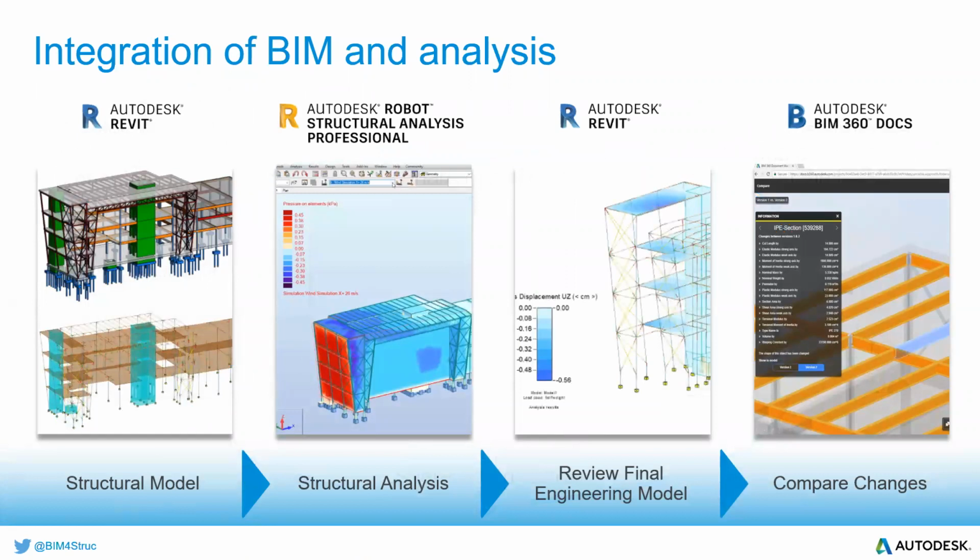So identification of the structural material, definition of the structural model, and this is with respect to the architectural model, where if you have time to look at the interface of Revit, you'll be able to see that you can directly link up the architectural model, then start defining your structural elements with respect to whatever the architect has identified in terms of their location, position, and even sizing sometimes. Immediately that's done, you can select to create your analytical model corresponding to the physical model that you created from the architectural model. So what that first phase shows us is the physical model and the analytical model.